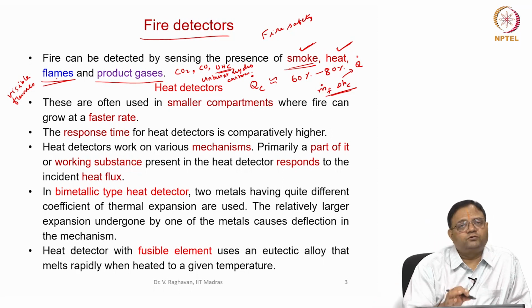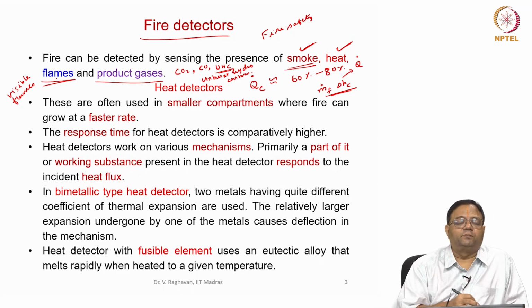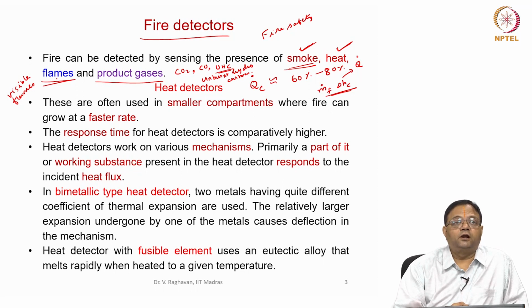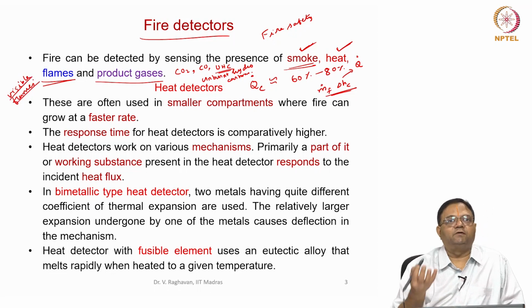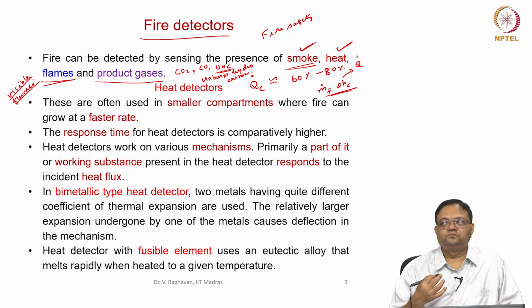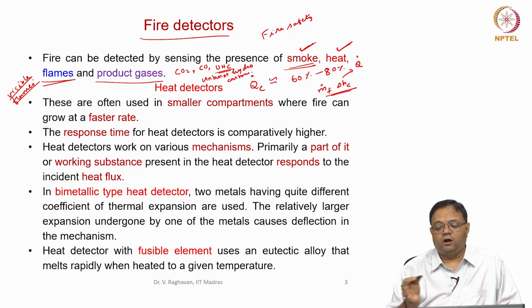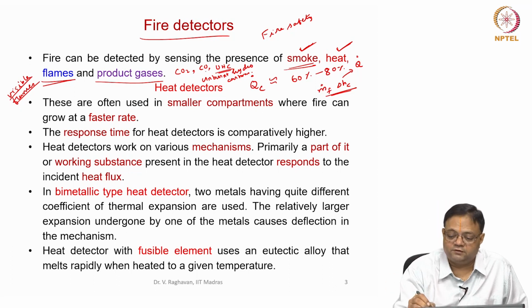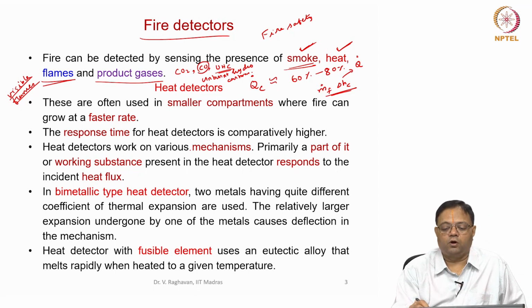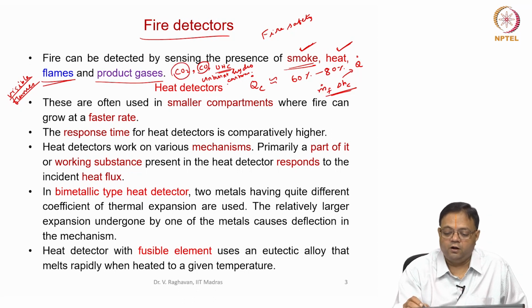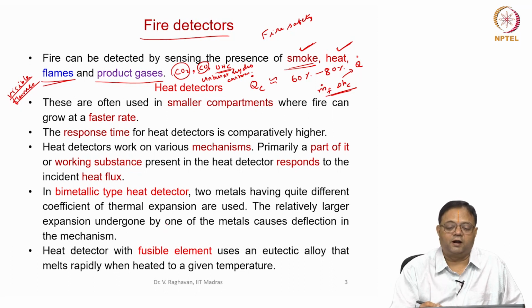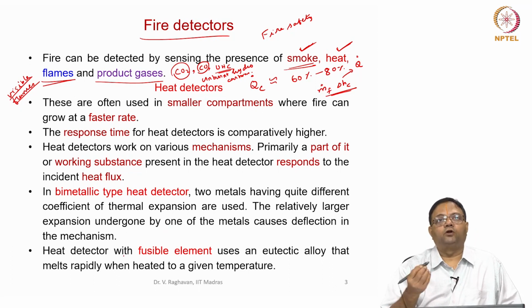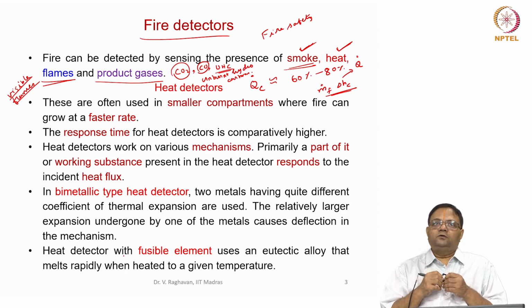If you can visualize flame, for example with infrared cameras, that will tell you the presence of a visible flame, and straight away you can say there is a fire. If these are not possible, and you have sensors to sense carbon monoxide, carbon dioxide or unburnt hydrocarbons present in the fire gases, then also you can detect the fire.